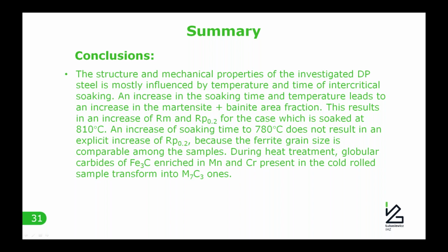works. So when we're planning the experiments, we do some experiments on dilatometry. Let's say we investigate the sample with a few CCT diagrams. We prepare the CCT diagrams, and when we have the ranges, we could test it on some other thermal cycles on the Gleeble.